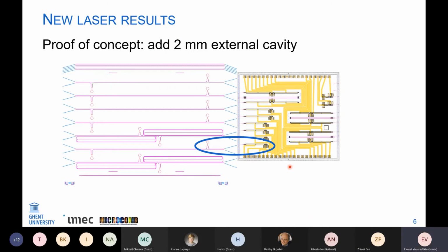So to actually show which cavity and RSOA we're using right now, on the smart chip we have several types of RSOAs. We have a few short gain sections of 850 microns with 2 different absorber lengths, and we also have a longer one, and we're trying to do some things with another, so not a Fabry-Perot mode lock laser, but a ring type mode lock laser. But we're not using those today.